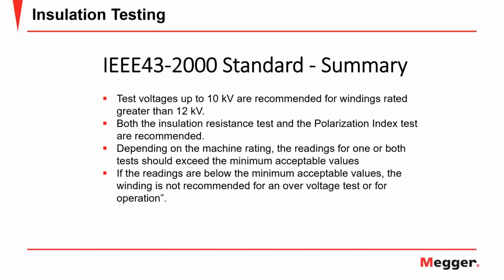And that standard, what it basically said was for very high operating voltage equipment, we don't demand that you have very high output voltages on your testers. 12 kV is enough. If you're testing 60 kV equipment, you don't have a 60 kV tester because it's impractical. With brutally expensive, large equipment, you don't need it. The IEEE standard said 12 kV is enough and you can test anything.